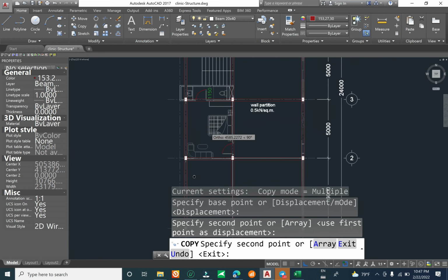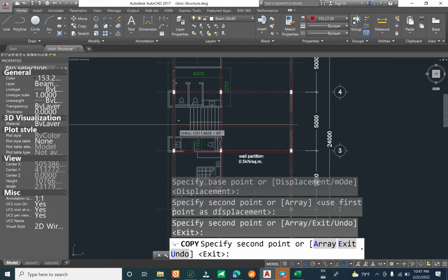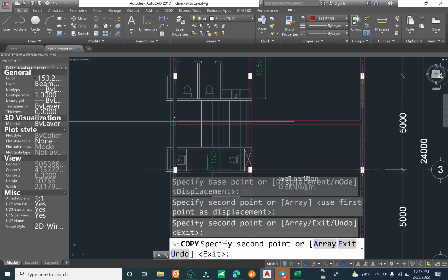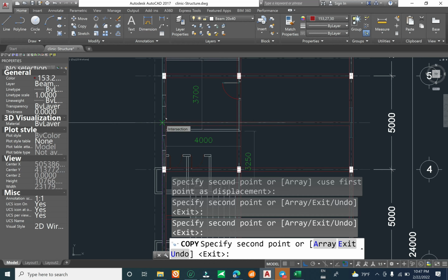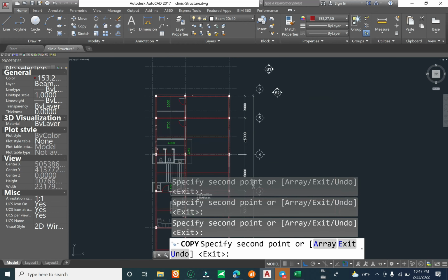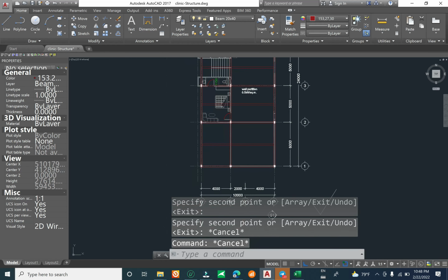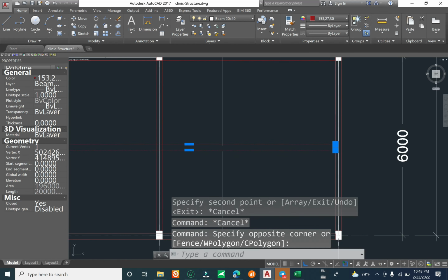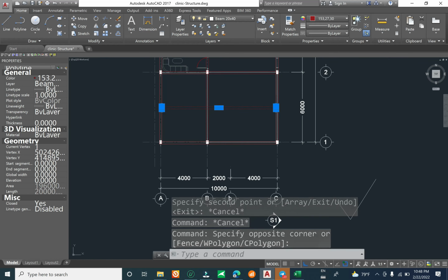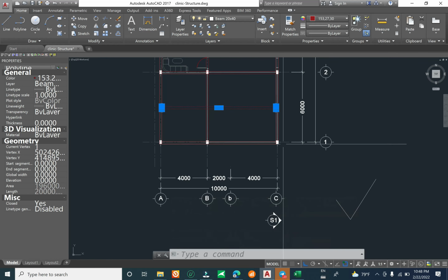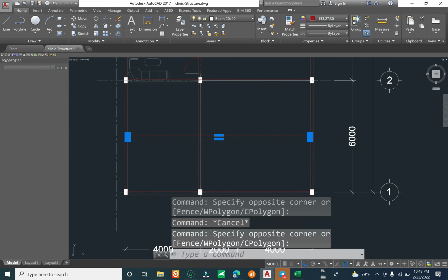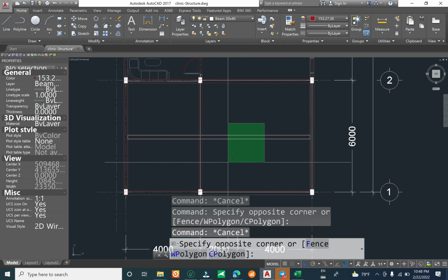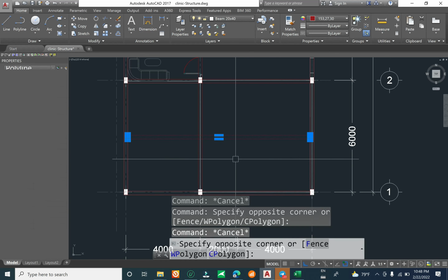Okay, this one, this one, but you can keep it if you like. You can keep it, but you have to extend to add more slab thickness if you don't want to use this beam. But for good recommendation, I recommend that when the slab panel area is over 30 square meters, you have to add a small beam. You have to reduce the thickness of slab and reduce the vibration from the floor.